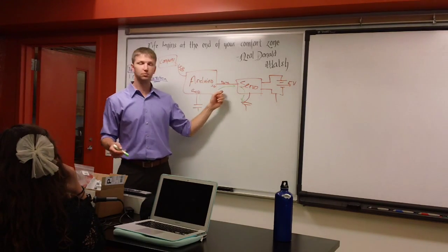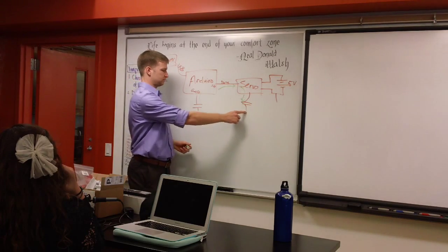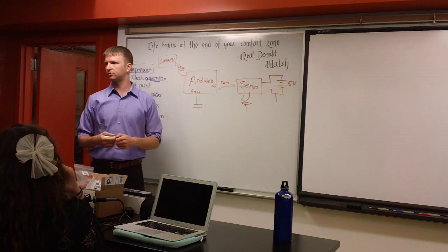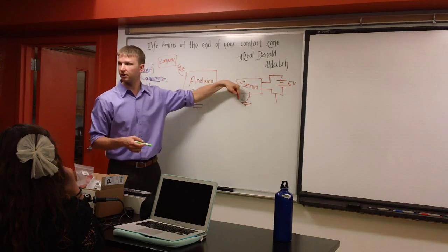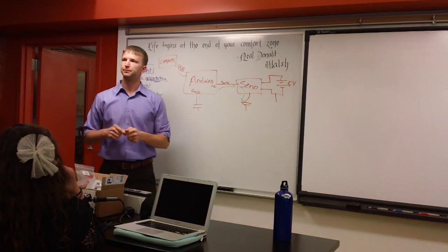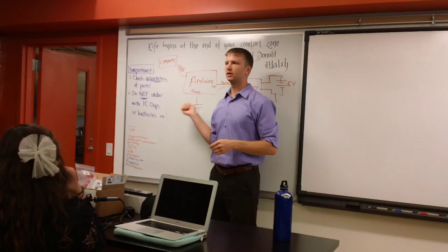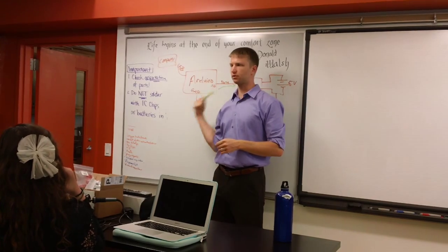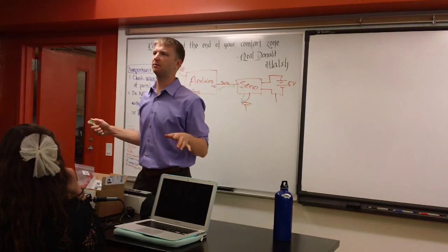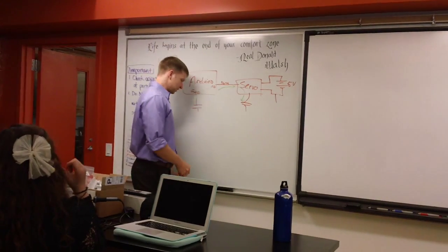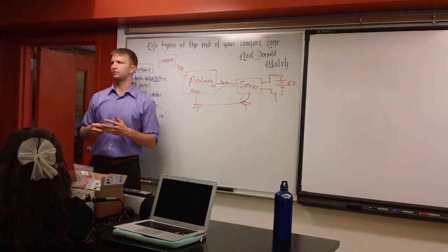Sometimes, if you had the signal moving really, really fast, you could make this connection here, but it would be silly to do. Why wouldn't you just connect the grounds with a wire? But you see that this is the end of the line for this current. Any other questions? Does that make sense? It's all about the loop. So the whole thing about ground is an easy way of talking about the wire that we connect to complete the loop. That's what ground is.